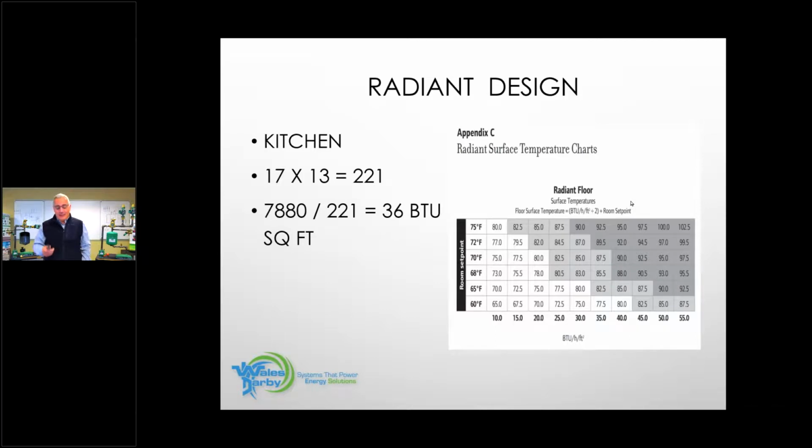All right. Now, believe it or not, in all the training I've had at Wirsbo/Uponor for radiant design, and I brought a lot of contractors out there over the years, we were always taught that 65 degrees was the sweet spot. And guys are going to say that's too cold, but think about how radiant works. We're heating the floor. If we heat the floor, it's going to give off radiant energy, and we're going to heat that person up to mid-chest level. We want them cooler from this point up.